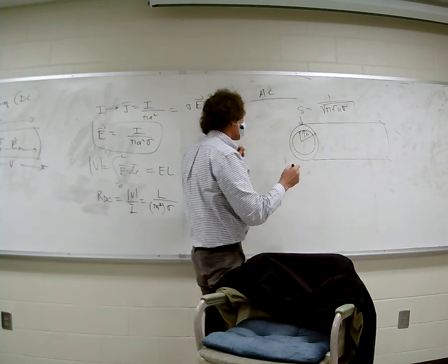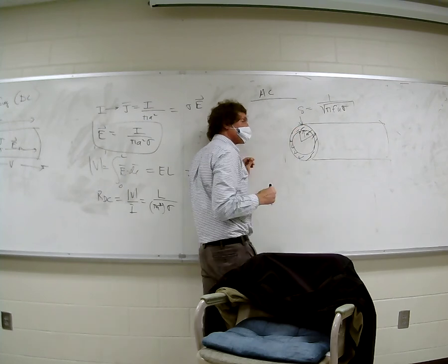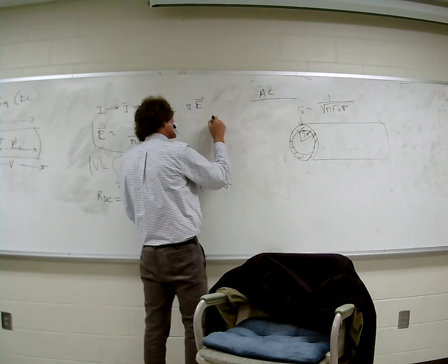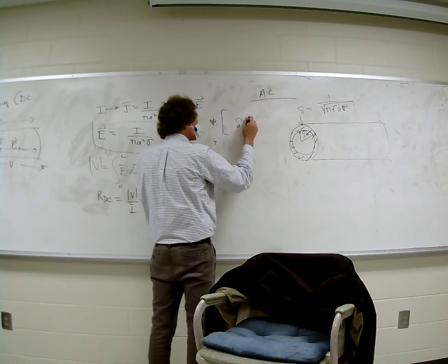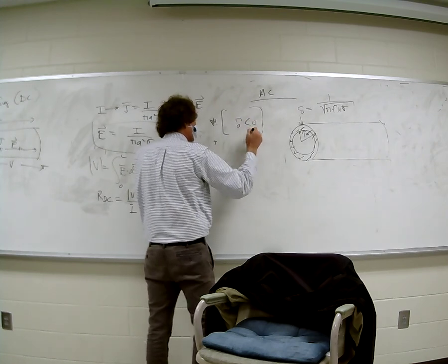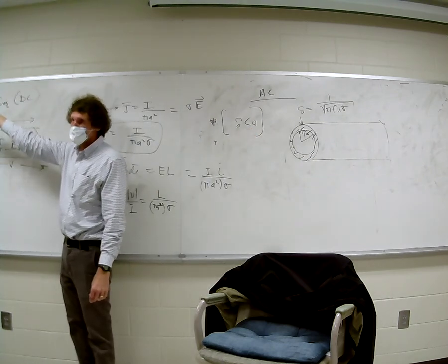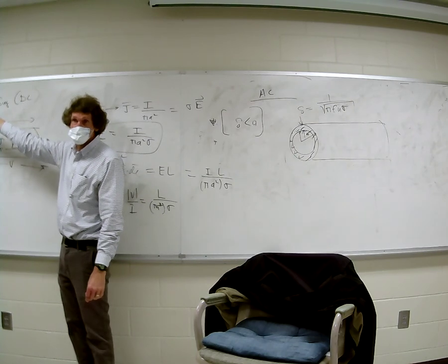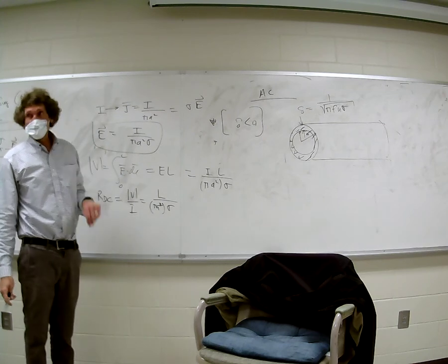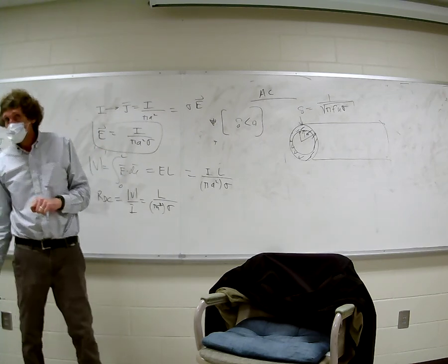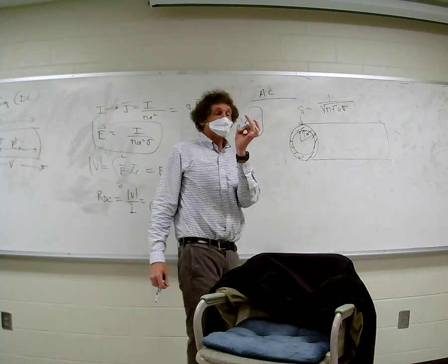All right, now I know all the current is really limited to 1 skin depth inside, but there's one qualifier. And put this down as star. We're assuming that the skin depth D is less than the radius A. Now, if the skin depth is greater than radius A, then you just default to that equation for resistance. And skin depth is inversely proportional to frequency. That's all it is. And very, very high frequency circuits that couple power basically are hollow pipes.